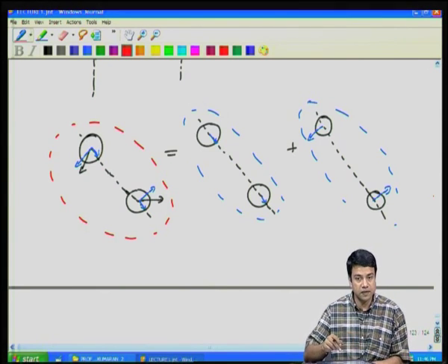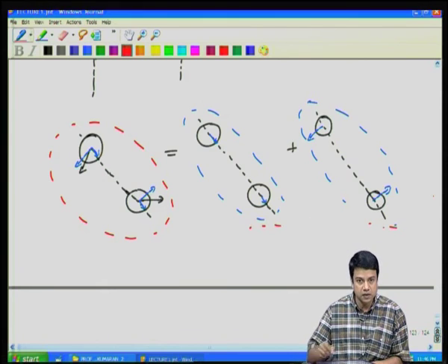That is, at each point in the fluid I can add up the velocity fields of these two problems. The result will be equal to the velocity field of the problem that I originally wanted to solve. That is because for these two sub problems, the velocity on the boundaries when I add these two up is exactly equal to the velocity for the first problem. And I know that if the velocity on the boundaries is added up, the equations are linear. So, if I add up the velocities for these two, the resulting velocity field also satisfies the equations of motion, that is the mass and momentum conservation equation.